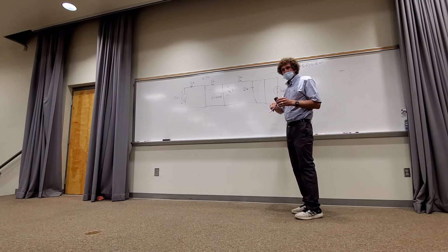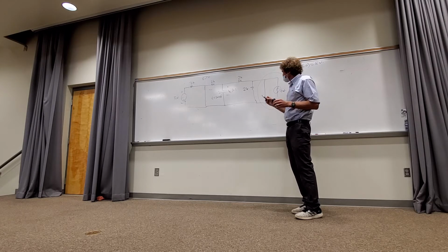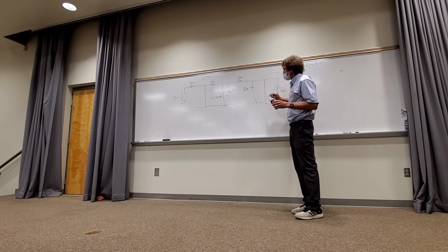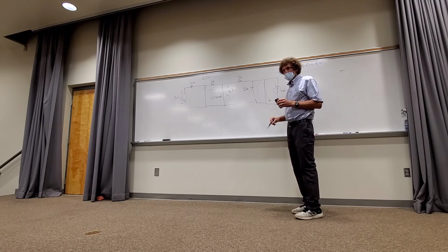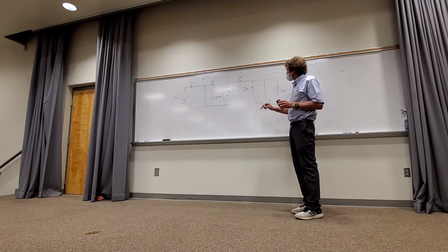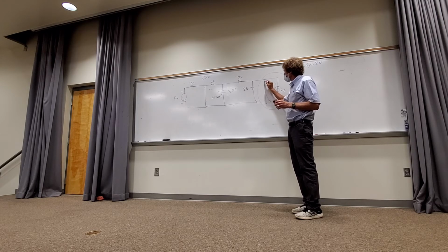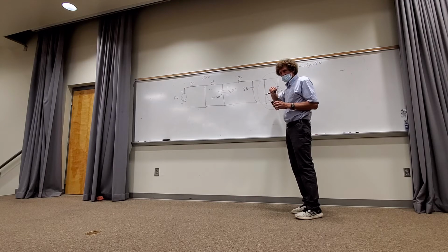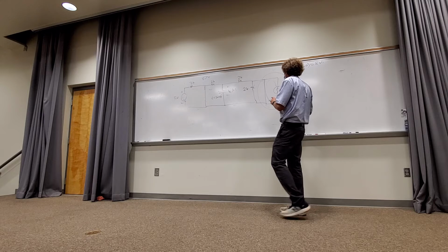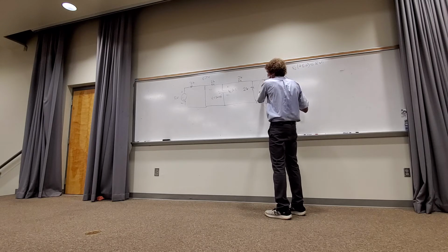Well, that's a short circuit, right? You see how all this current has to circulate around there? Effectively, it takes this point that's shorted to ground, and it shorts it to ground. It gets rid of this resistor entirely. Do you all see that? Yeah, that switch shorts to ground, so this point becomes grounded.